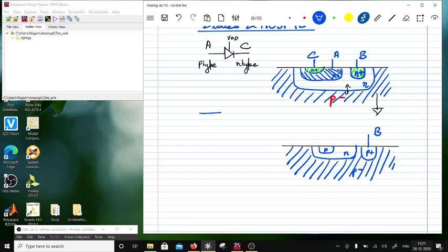You have an anode, which is the p-type side, and then you have a cathode, and then you have a body terminal which will be connected to ground. So now this whole substrate is grounded, and you can make these contacts. These are called substrate contacts. You are going to make these contacts all around the device. And then you have this as anode, this as cathode. So this is going to be your device, which is sitting outside the well.